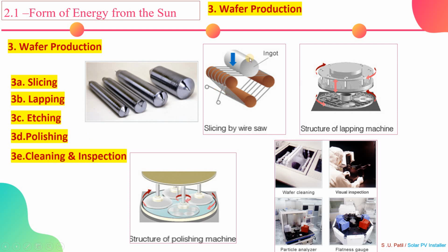In slicing, as you can see, silicon ingots are sliced into very thin wafers using diamond coated wire saws. The circumference of the monocrystalline crystal is ground down to a uniform diameter. Based on the resistivity desired by the customer, the ingot is then cut into slices of around 1 mm thickness using the inner diameter saw or wire saw to form the wafers. After the wafers are sliced, a process called lapping is performed to remove any saw marks and surface defects. This also thins the wafer and relieves it of the stress from the slicing process.